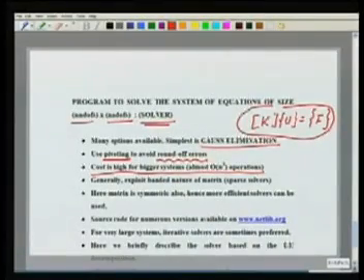In fact, most of the direct solvers, which work by simply doing an elimination, do have a very high cost of solution, and it is of the order of n cubed. n is the size of the system, so it is nndofs cubed. So if nndofs is increasing, the size is becoming bigger and bigger, the computational cost is going to become bigger and bigger.